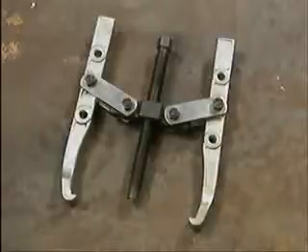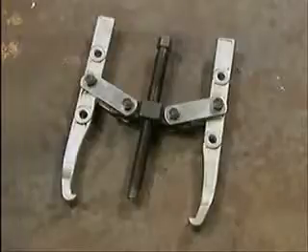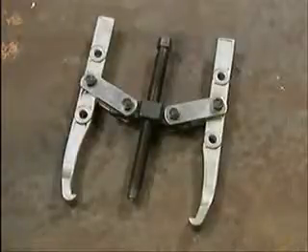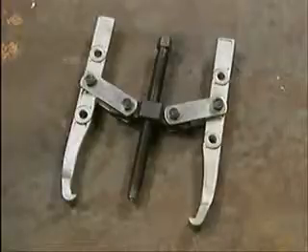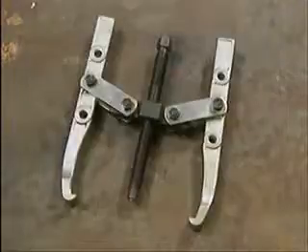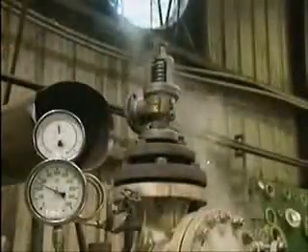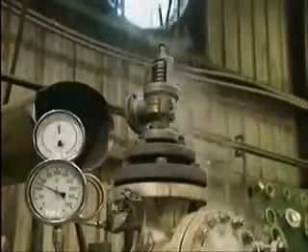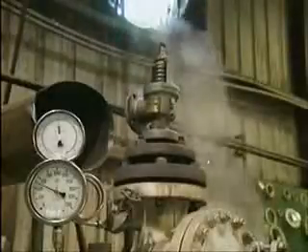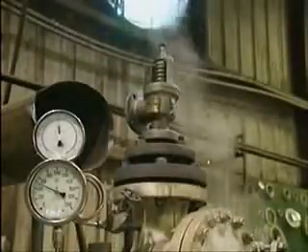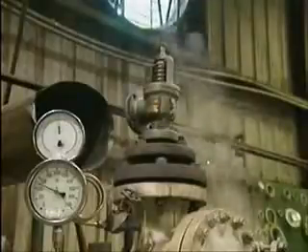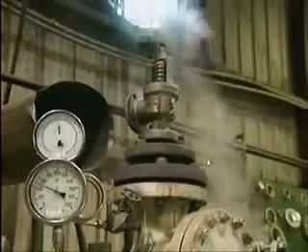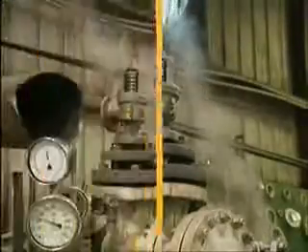Next, prepare to perform the necessary tests. An important preparation for many testing procedures is gagging the valve. Gagging involves installing a device called a gag that keeps the safety valve from opening during testing. We'll look at a typical procedure for installing a gag on a 2-ring huddling chamber safety valve. The valve's release lever and the protective cap have been removed so the top of the valve stem is exposed.